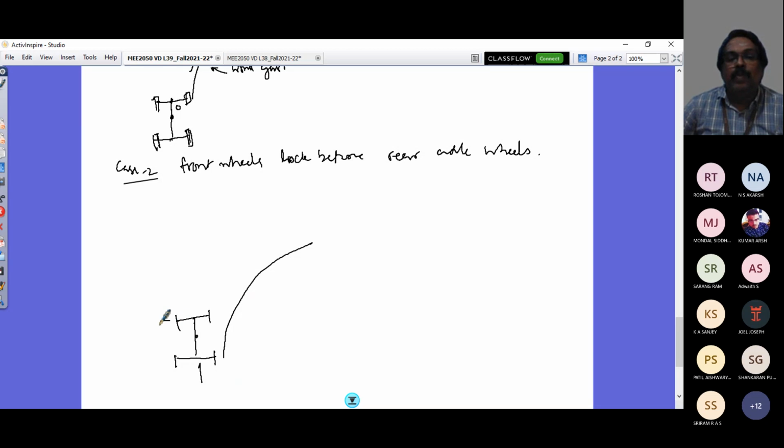And now this would be drifting here because these wheels are locked, but the rear wheels are rotating. So this is your yaw center O, and you would have a total braking force acting in this, and the scenario changes like this. So the distance here, you'll have your FB, and this is your WA by G.